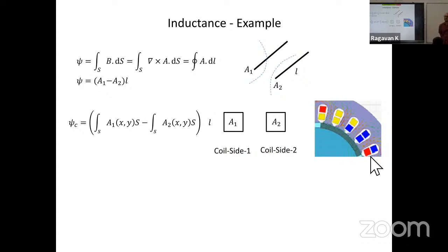Okay, let's take a similar example. Let's say I have a transformer. We always say that an induction motor is equivalent to a transformer. So if I short the secondary and then measure the inductance on the primary, is it the phase inductance? Is it the primary inductance? No, right? Does everybody agree that if I short the secondary and measure the inductance, it's not the phase inductance? Similarly, in the induction motor, if you take the motor as it is and just measure the inductance, it's not the phase winding inductance.